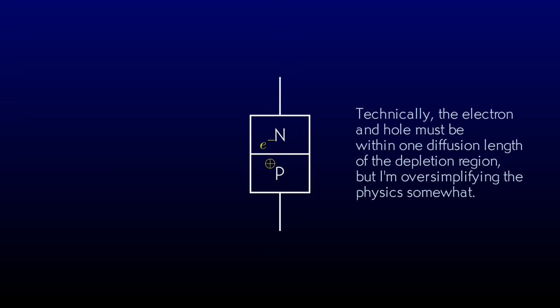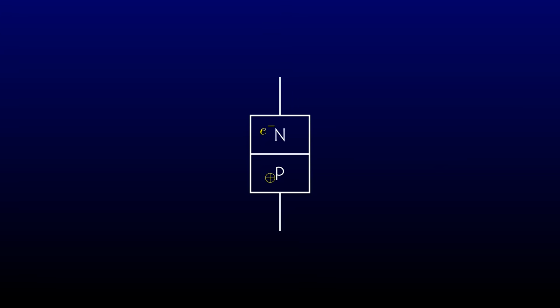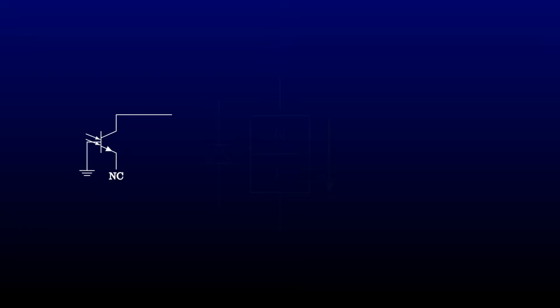The photodiode works because when photons hit the semiconductor, they transmit energy to electrons, which can get shaken loose from the lattice and absorbed somewhere else. The resulting electron-hole pair can be on opposite sides of the junction, leaving the electron and hole free to migrate. The cumulative migration results in a current in the reverse direction relative to the diode's orientation. We'll take that current, called a photocurrent, and feed it into our circuit.